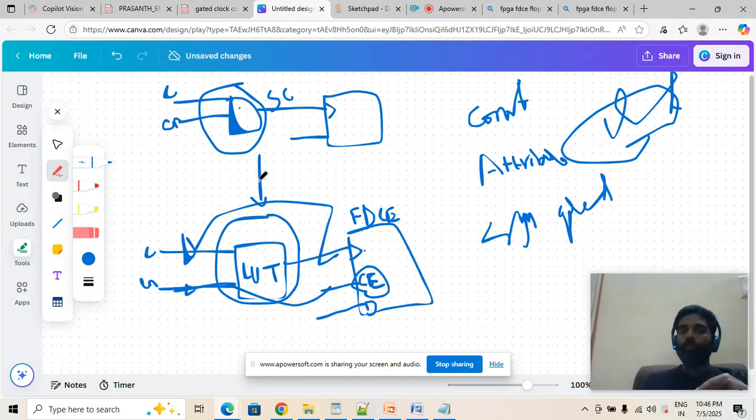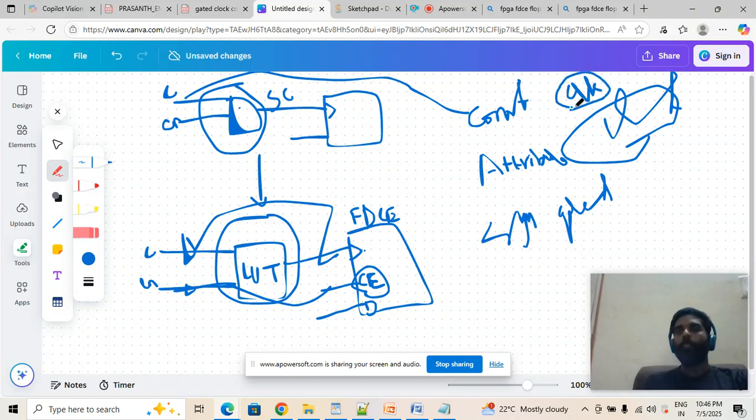When you provide this clock as your constraint, for example, this is my CLK port, the clock port, I'm writing one create_clock constraint here. The tool can understand the constraint directly. When you enable this synthesis option, which is compulsory, the tool will understand that this clock should be treated as a clock gating.